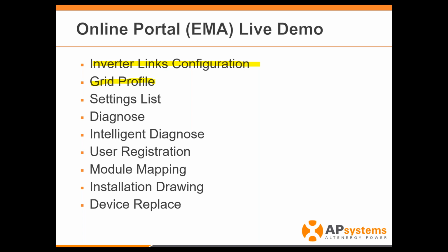Depending on your jurisdiction, I know that in Canada, we're using the UL 1741. And California, for example, uses 1741 SA. I don't know if Canada has adopted it yet, but I'm sure it's coming. So this is where you'd be able to go and actually change those numbers easily.